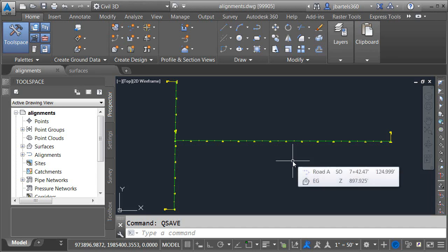One of the ways Civil 3D manages the dynamic links between project data is through the use of data shortcuts. Generally speaking, data shortcuts allow drawings to share components like alignments, surfaces, profiles, and pipe networks, rather than having to squeeze all that information into a single file.